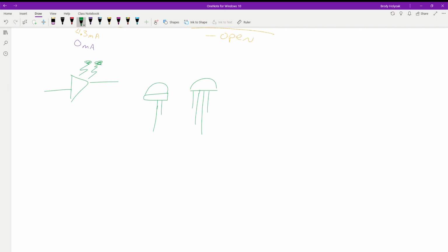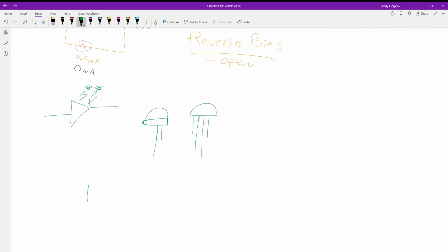is you'll have a round spot over here, and then on one side you'll see the flat. The flat is connected to the shorter side when you first get them. But if you cut them, you have to go based on the flat. The flat is the negative. Okay? So with the 3-color ones, this one just allows current to go one direction.